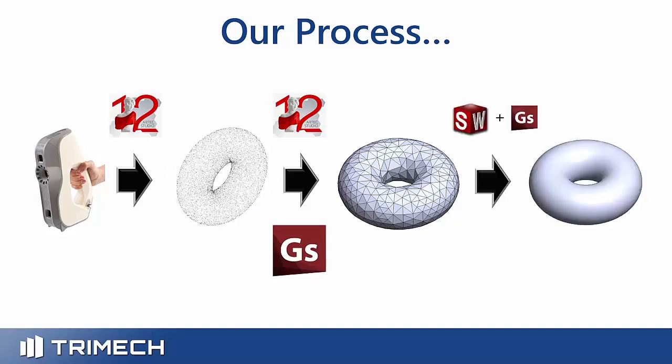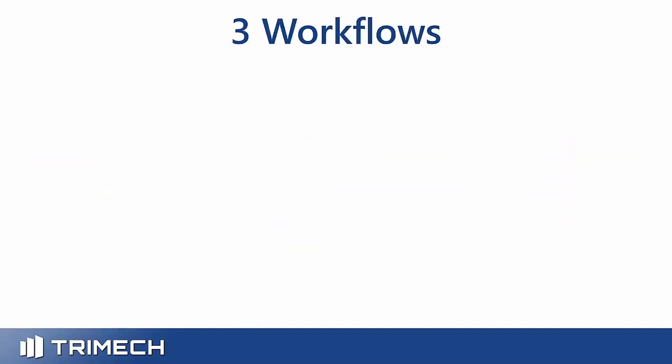We'll assume that we bring this 3D tessellated geometry as an STL file into SOLIDWORKS using the Geomagic for SOLIDWORKS plugin, and then convert it into a 3D solid that can be used normally like any other SOLIDWORKS part.